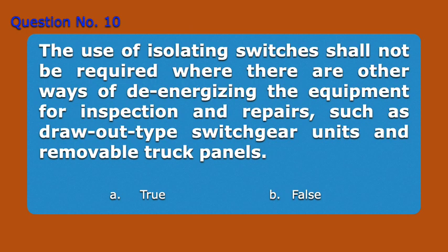Question number 10. The use of isolating switches shall not be required where there are other ways of de-energizing the equipment for inspection and repairs, such as draw-out-type switchgear units and removable truck panels. A. True. B. False. Answer: A. True.